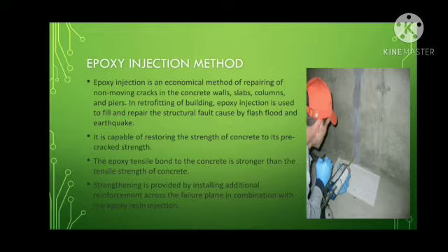Next, we have the epoxy injection method. Epoxy injection is an economical method of repairing non-moving cracks in concrete walls, slabs, columns, and piers. In retrofitting of building, epoxy injection is used to fill and repair structural faults caused by flash floods and earthquakes.